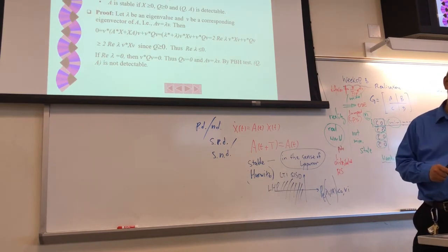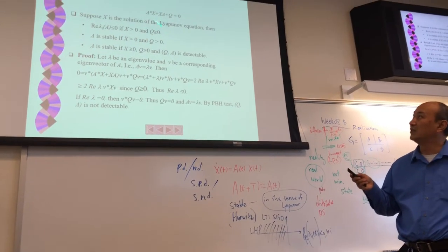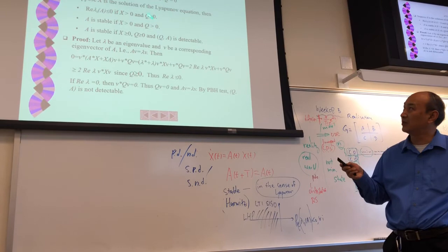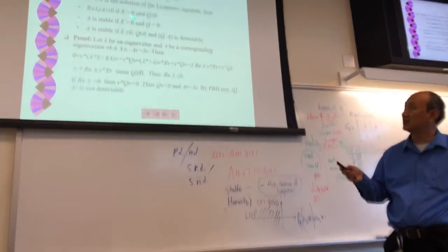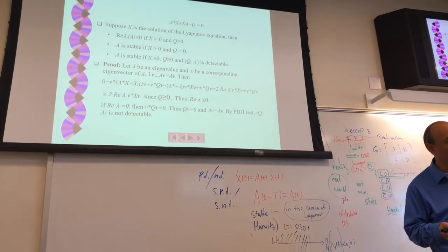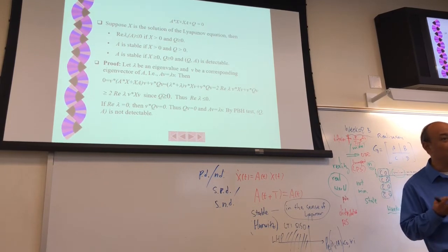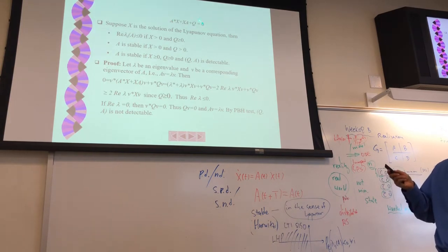There's a way you can, without solving the eigenvalues, by checking this Lyapunov equation. If you are given a Q semi-positive definite, then you solve and X is positive definite, then that already implies A is a stable matrix. So that offers another way to check the stability of a matrix. You just try to solve the algebraic equations for X. X has n by n unknowns, so you just solve these matrix equations.